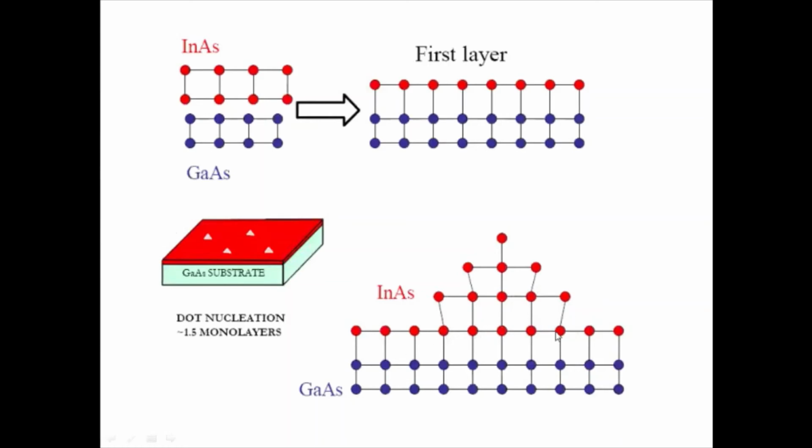Here the initial layer thickness should be less than the critical layer thickness. In the initial stage of the epitaxial growth, I told you that for relaxation of the interfacial stress, it should cross the critical thickness or critical layer thickness. Once it crosses the critical layer thickness, then relaxation of the stress or strain present at the interface will occur. So you have to grow this initial layer so that the thickness is less than the critical thickness for this system. That you will have to calculate, right? Okay. So because the thickness is less than the critical layer thickness, the stress or strain is not relaxed. So you will have the stress coming out in the form of buckling.